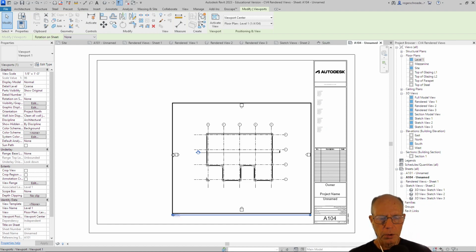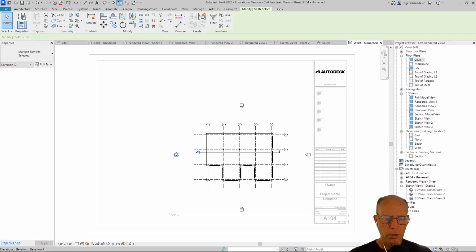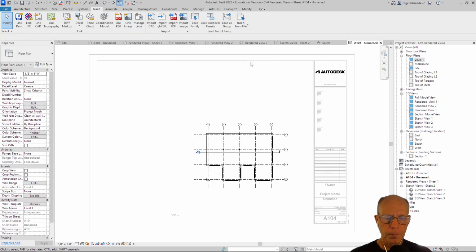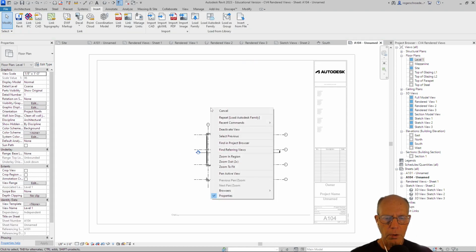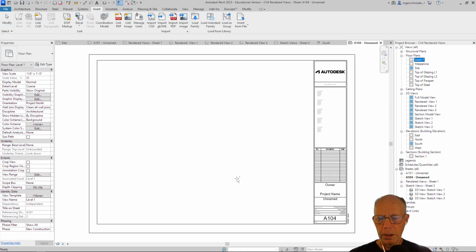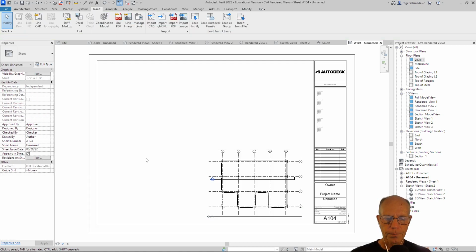We have these tick markers for the elevation. So I'm going to click into this and get rid of those right away. So I'm going to select all of those objects and go hide in view by category. And it looks pretty good. So I'll right click and deactivate it, and I'll delete it and drag it back on again. And there we have our level 1 on our technical drawing sheet.